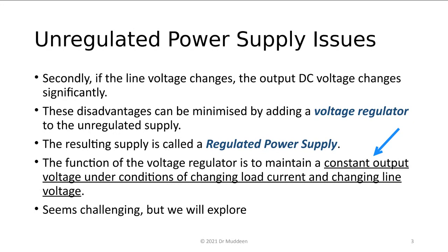If instead of 5 volts it's giving you 4.5 volts, then when the circuit switches, it's not going to get into a voltage level that will be considered as a valid high, and you run into problems. So the whole idea of regulation is extremely important when it comes to powering devices like logic devices that require a certain voltage to be interpreted as a high.